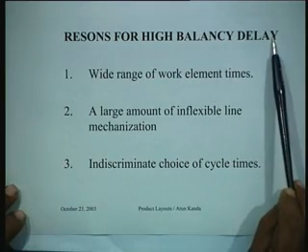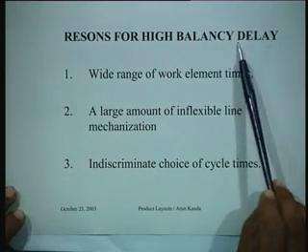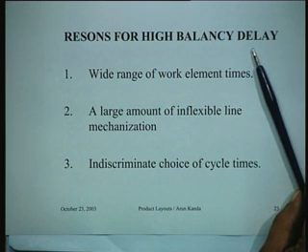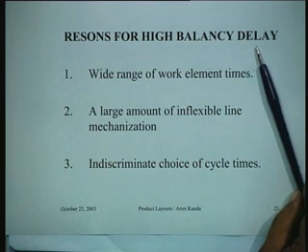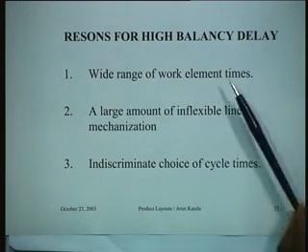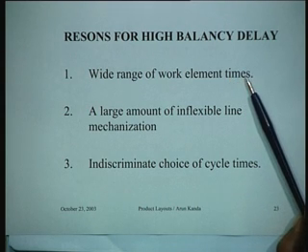The question now is, what are the possible reasons for a high balance delay? Balance delay measures the line inefficiency, which means the degree of idle time which is there for the various operators. Some of the reasons for this are: number one, the wide range of work element times.